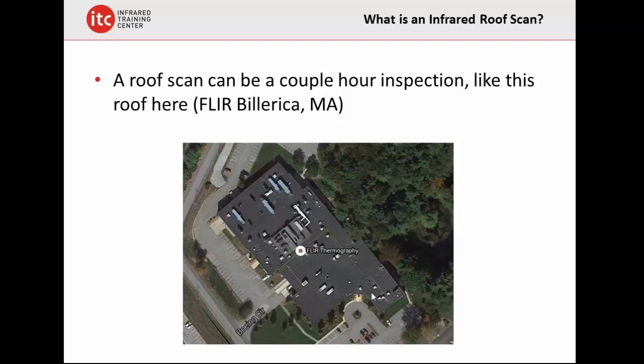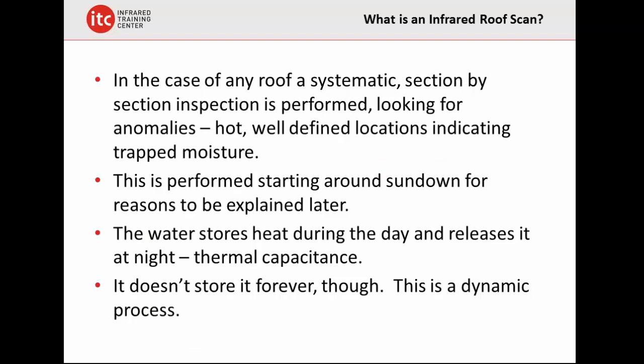And then I would go in a zigzag pattern back and forth, but again, in a clockwise fashion, and do a very, very systematic scan, stopping and storing images of every anomaly that we found, and going again in a clockwise fashion around every single HVAC unit. By always keeping that same systematic clockwise motion, never going counterclockwise, you're always guaranteed to get 100% coverage. If you start to go randomly, you're going to miss that one roof leak, and that one roof leak is probably going to be over the general manager's office or the CEO's office, and there goes your credibility. Okay, so we want to always be systematic.